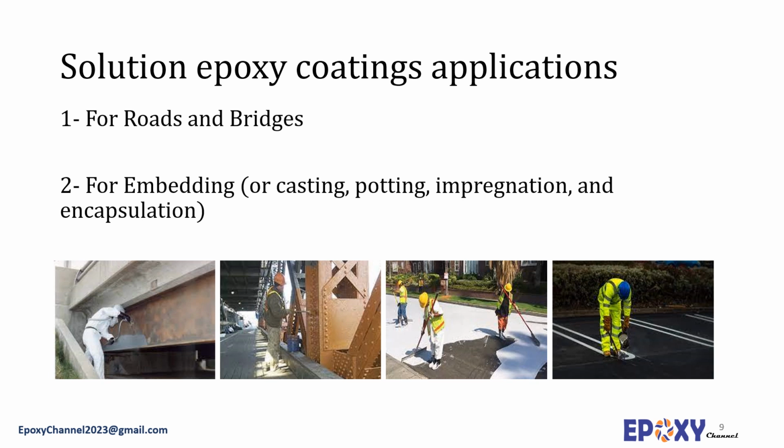Cycloaliphatic epoxy resins, which have been cured with anhydride hardeners, exhibit excellent weatherability and contain no chlorine and aromatic rings. These systems are perfect for encapsulation. In these systems, fillers such as silica, talc, clay, and calcium carbonate, mica and chopped glass can be incorporated.